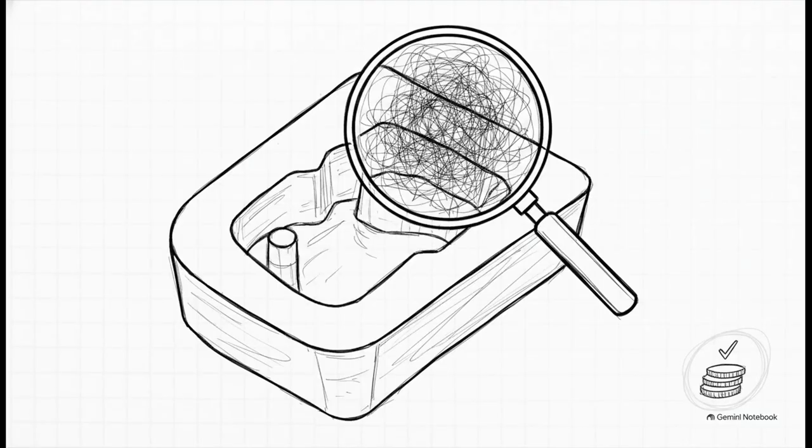It wins every single time. Honestly, applying a uniform, microscopic tolerance across an entire massive surface is just a great way to bankrupt a manufacturing project. Instead, we use the composite profile framework. We combine a looser overall form and location control for the general surface with tighter, localized zones in functionally critical regions like sealing surfaces or leading edges.